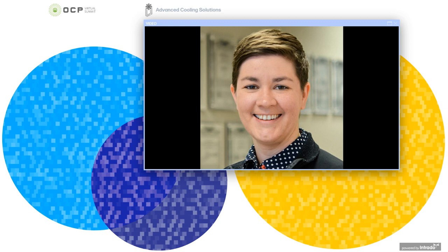But prior to all that, one thing you can do is reach out to your QD supplier and ask for a validation report. This is something that CPC does, and it's a very comprehensive test protocol and report that will cover the whole gamut of performance for the fitting. So it might include mechanical performance testing, such as force to connect, side load strength, cycle testing, some thermal performance for high and low temperature scenarios that might be to cover shipping and preconditioning environments or high temperature environments that might accelerate some things. And then of course flow and leak testing.